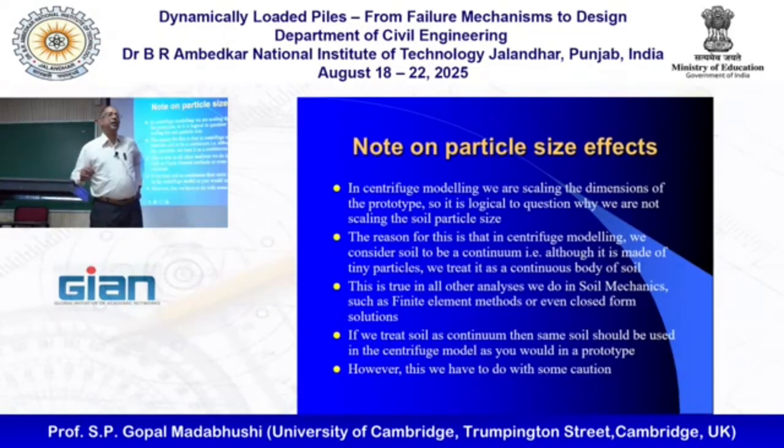The funny thing about soil mechanics is we all know that our particles are individual particles, but all our theories come from continuum mechanics. For the 50 years till now, we somehow managed to bridge across that and say theories developed for continuum mechanics can be applicable for soil because we measure gross properties. And it's the same here. You just need to make sure that your pile is of reasonable size and you've got enough particles in contact. So don't do this test at 150 G, do it at 50 G. Then you get a 20 millimeter diameter pile and enough particles in contact.